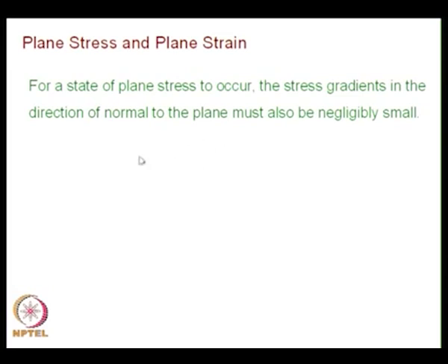And you will also have to note, for a state of plane stress to occur, the stress gradients in the direction normal to the plane must also be negligibly small. This condition is not completely satisfied even in thin plates.